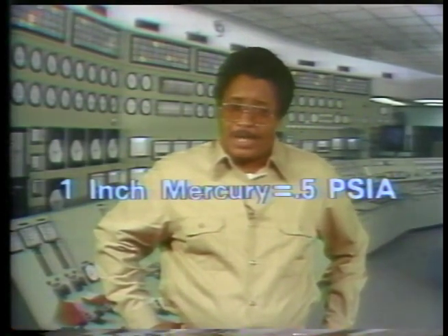In our example, we showed you how gauge pressure related to absolute pressure. We could just as easily have shown you how inches of water, inches of mercury, or any other units of pressure related to absolute. For example, a 1-foot column of water exerts a pressure of about 0.43 psia. The conversion factor, then, is 0.43 psia for every foot of water. If you're measuring in inches of mercury, the conversion factor is 0.5 psia for every inch of mercury, because a 1-inch column of mercury exerts a pressure of about 0.5 psia. We've rounded off these numbers to make our calculations easier. But you must keep in mind that while approximate is good enough for what we're doing, in the plant you'll need to use exact figures for any calculations you make.